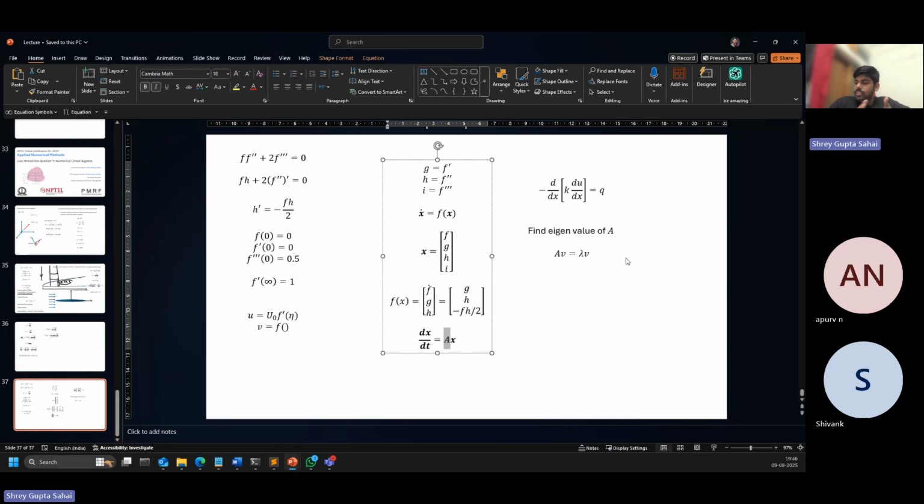So in that picture you have this stiffness tensor. Always a tensor is operating on a vector, giving you another vector. There is a special set of directions for every tensor along which it does not rotate the vector. It only stretches or compresses the vector. The amount by which it stretches or compresses the vector is called the eigenvalue. The directions are called eigenvectors. That is the whole picture. That is the whole idea there.